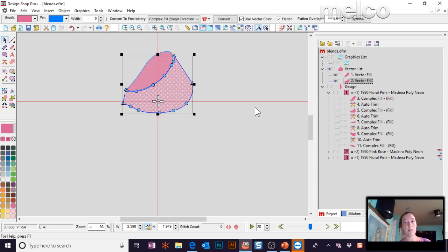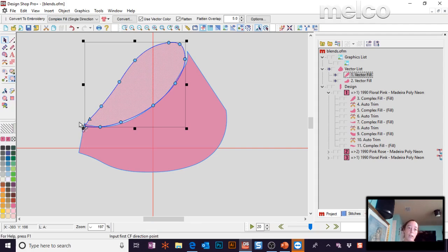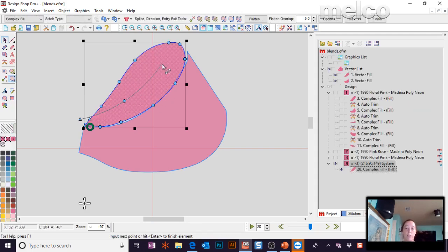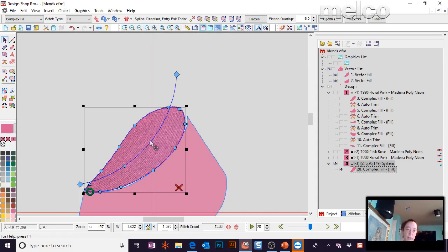So to create them, what I would do is draw the shape. So you can just use your regular, and if you're not going to use a vector, you can always use a complex input where you draw your shape. I'll do that in a minute. But just for this one, if you select the shape you want first, after you select it, you can then hold down this Insert Stitch Direction button, and you'll come over to the second one, which is Insert Curve Stitch Direction Line. Okay, when you do that, now I can left click for straight points, right click for curves, and that'll allow it to curve around. So if I put it in 3D, you'll see now the stitches are curved.